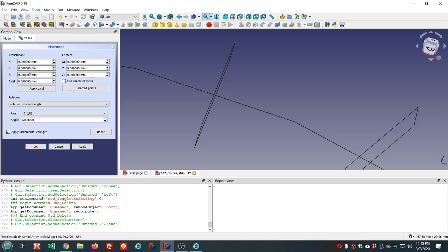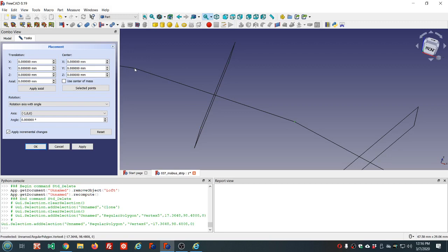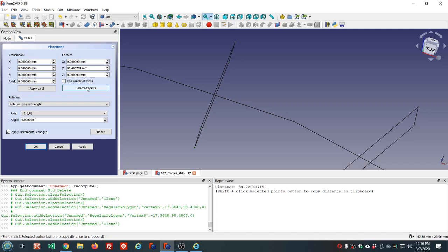That's going to clear all this out, and that's going to let me move it relative to where it's at right now. And I'm going to select these 2 points to create that axis. But I'm not rotating, I'm moving along this axis of rotation. And I want to go a very small amount the other way. Alright.